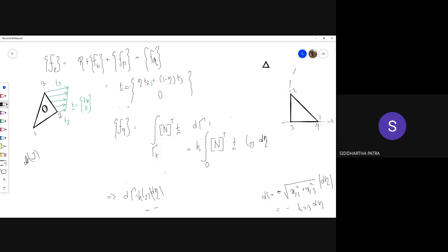Okay, that is, if all the finite element softwares are working with that thing, that is fine. Otherwise, let's say you are working in a given software which takes clockwise numbering, okay, and the negative determinant of Jacobian as the convention, and then you shift that model to some other finite element software, and that software throws you an error that some elements or most elements or all elements are having negative Jacobian, which is an indication that the element, let's say a simple tetrahedral element, is actually flipping. Okay, now what is flipping? Let's say this is your tetrahedron. Okay, this is a tetrahedral element.